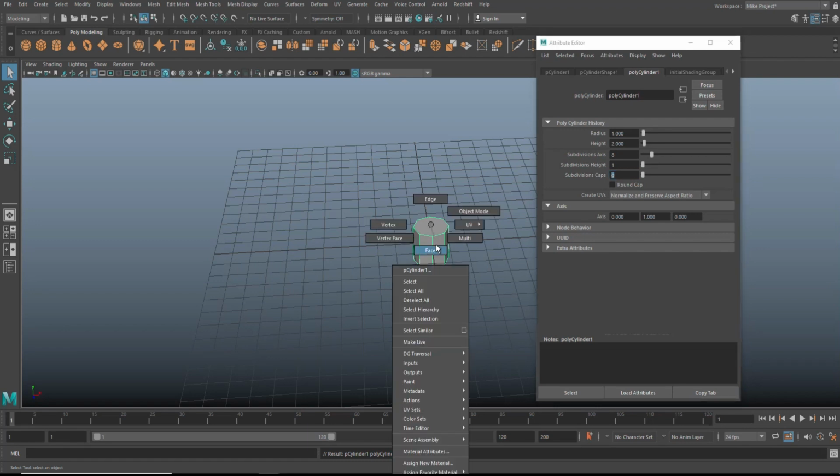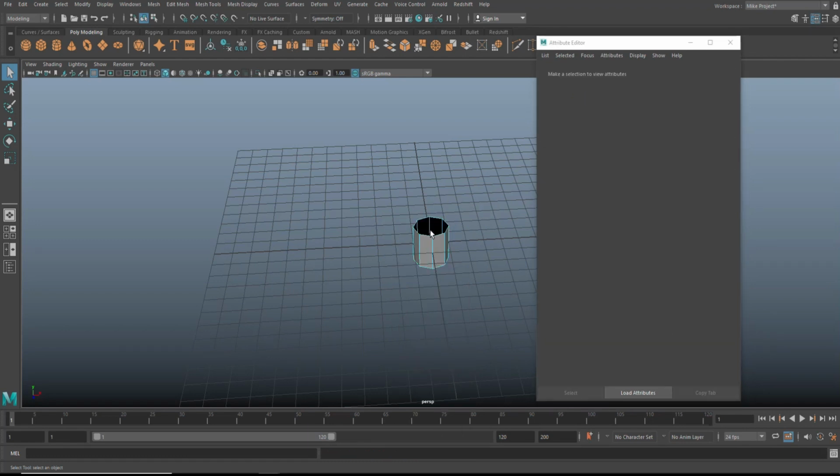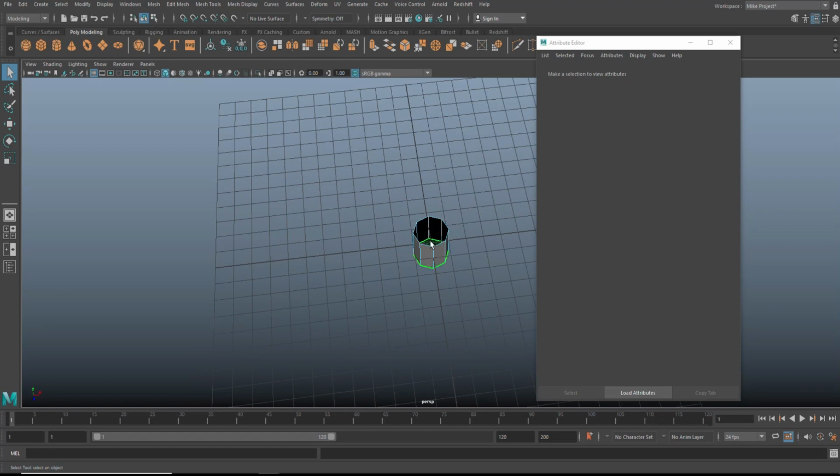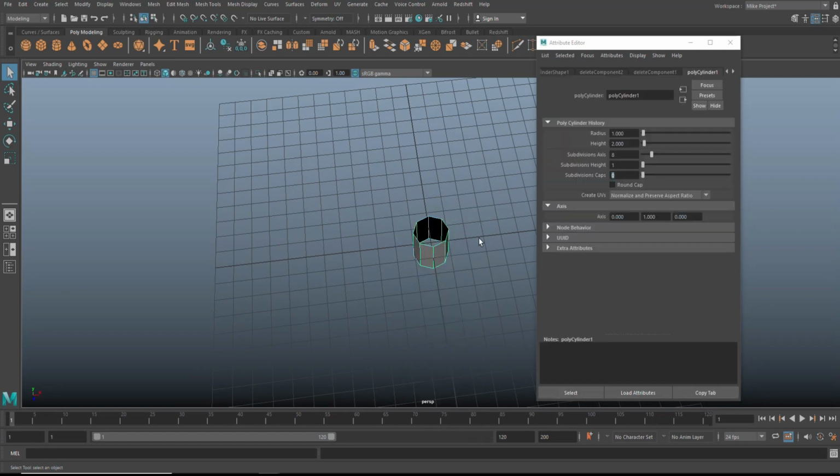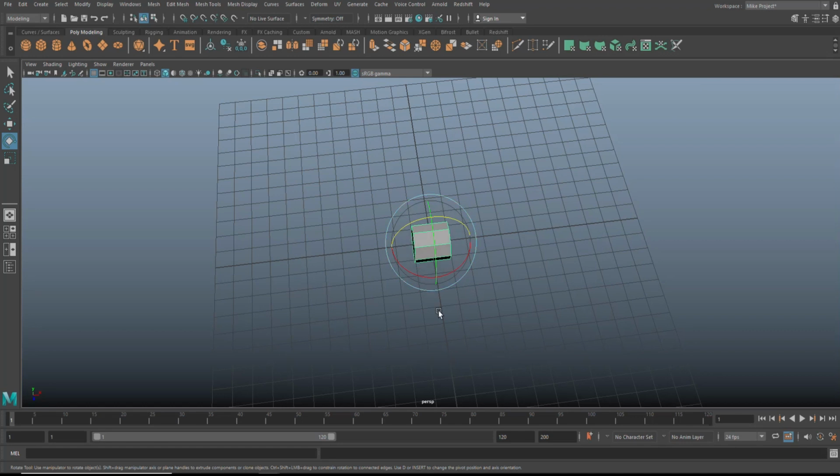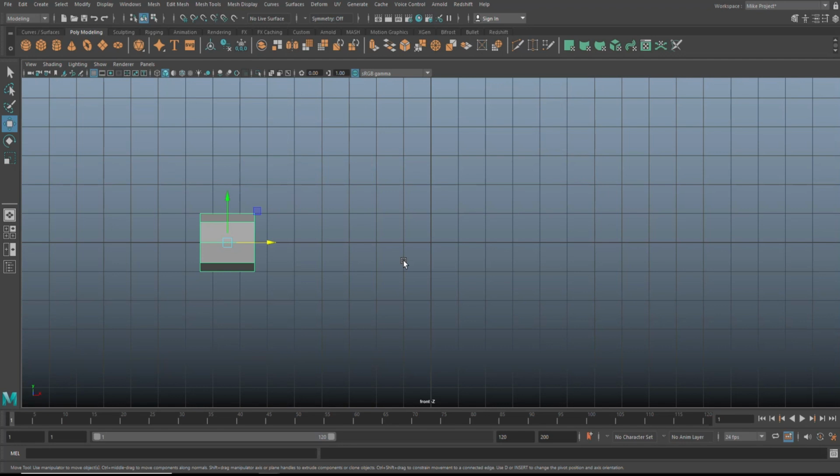I'm going to right click, go in here, go to face, delete that one, and delete that one, and then I'm going to take this guy, either rotate, hold down J, and snap it like that. Okay. I'm going to move a little bit to the left like so. Then we're going to jump into this view. I'm going to right click on a vertex, drag select. Let's push that in. Let's hit R and scale it up like, yeah, probably like that.